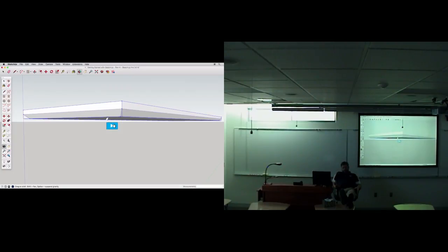And you will not be able to connect this object to anything in your design. This object will be free to move around on its own. It will not be integrated into any other part of the design. And this is how the 3D Warehouse works. When you design something for the 3D Warehouse, it creates objects from those things, and then you can import those into and out of other things. So it's pretty simple. You right-click, you go to Group, and you create a group.